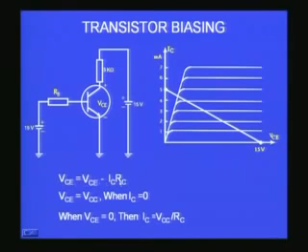So, this is the DC load line, that is what I showed here, but how, for a given value of RC and VCC, will I get a very specific load line? How do I do that? Now, let us assume IC becomes 0, that means there is no current through the collector. When will that happen? That will happen when there is no base current, or the base current is too small to switch on the transistor, to forward bias the transistor. Then IC will become 0. When IC is 0, then the voltage IC RC is also 0, because anything multiplied by 0 is 0.